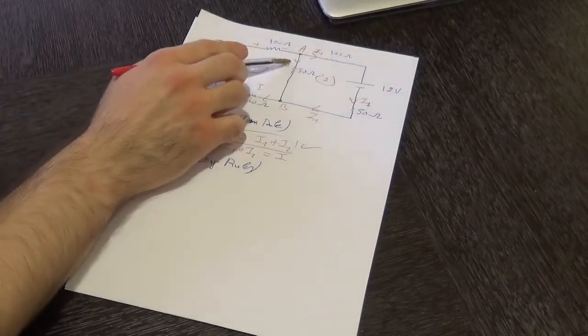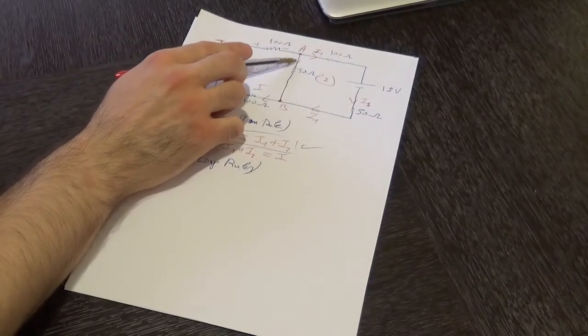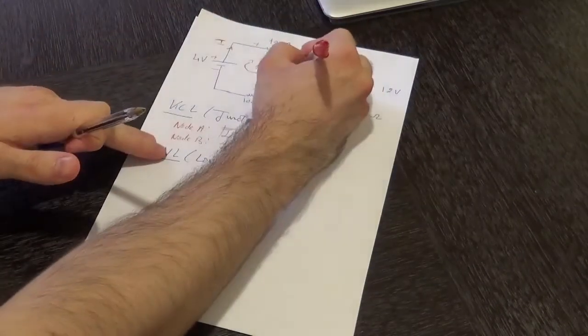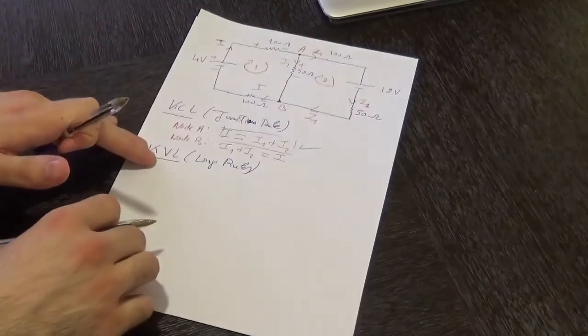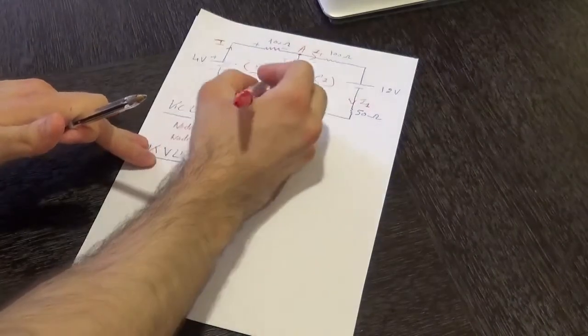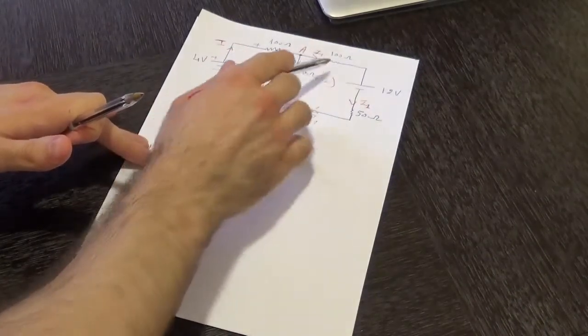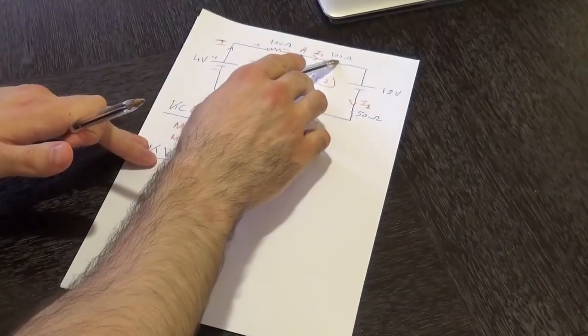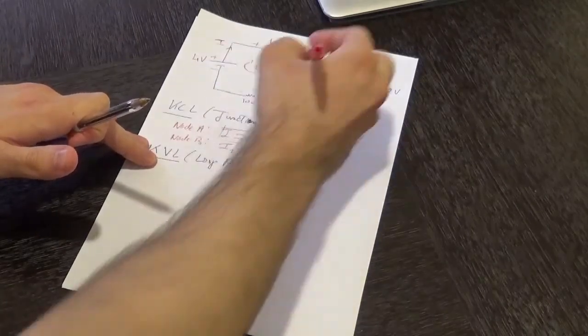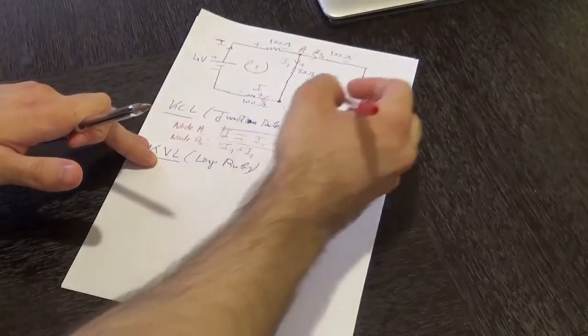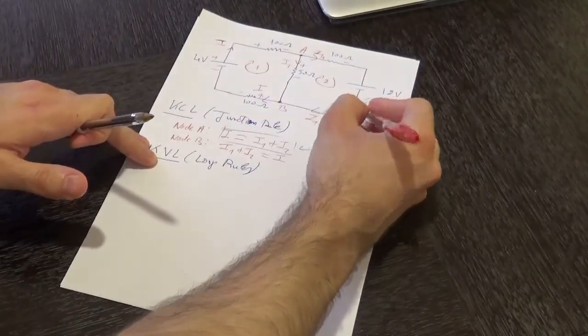In a similar manner over here, I2 is entering that resistor from that side, therefore that part would be the positive terminal, and the other side of the resistor would be the negative terminal. And in a similar manner over here we have positive and negative. Then I1 is entering the 100 ohm resistor from the left side, therefore the left side would be positive, the right side would be negative, and in a similar manner over here we have positive and negative.